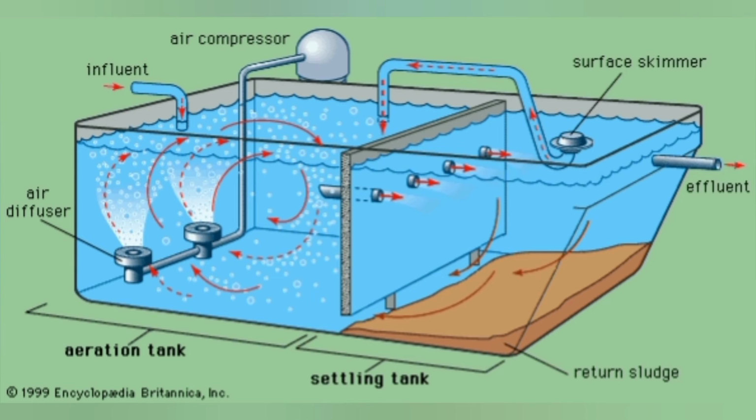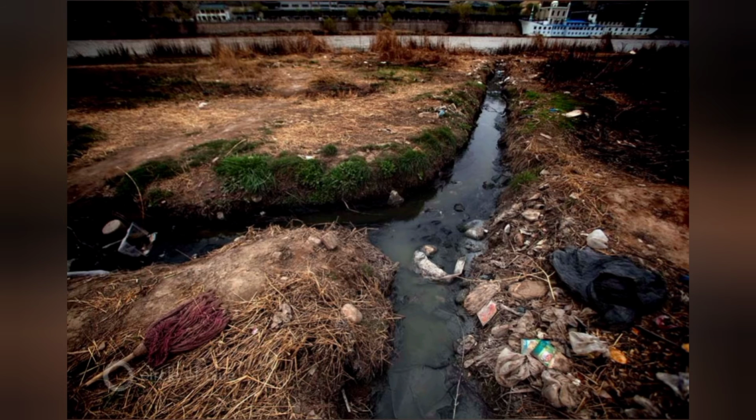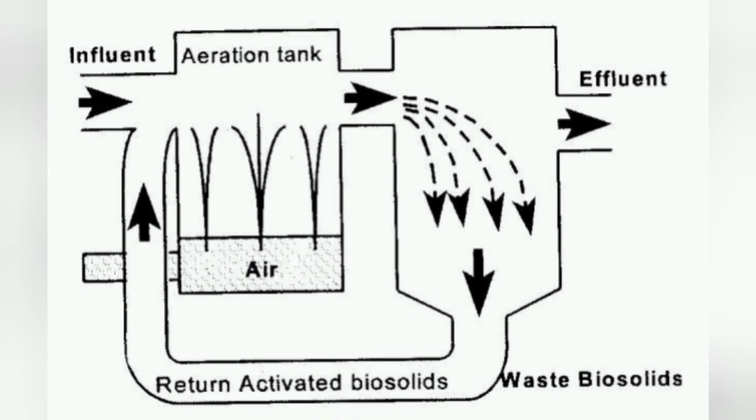The system is also determined by the amount of treatment required to keep the quality of the receiving streams and rivers. Sewage treatment requires chemical, biological, physical and sludge treatment methods. The result is clean sewage water and sludge, both of which should be suitable for discharge or reuse back into the environment. The primary treatment here is a physical treatment process that takes place in a tank and allows substances to settle or float and be separated from the water being treated.